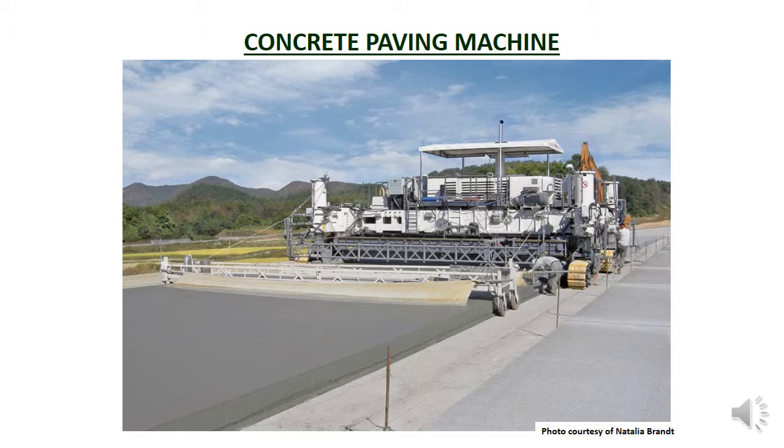Concrete trucks deliver concrete to the site and discharge into the hopper on the far side of the paver. The concrete is distributed across the width of the road and then laid in an even layer on the road. The depth of the layer can be set to accommodate the different depths. The screed at the back, which is facing us, provides a final trim of the surface and smooths it. The fabric at the back is hessian that is used to provide a smooth finish.